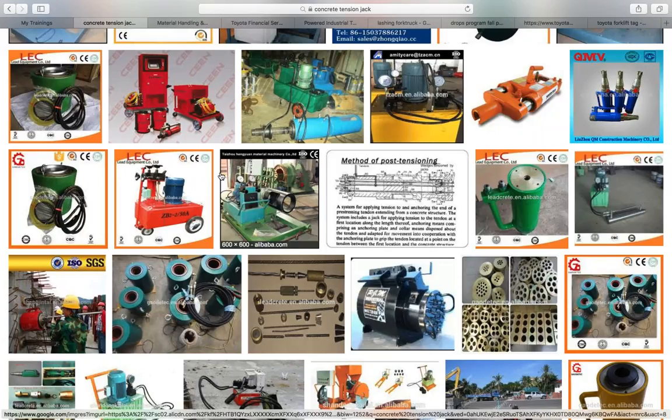We know that. Formwork has to be erected and braced in a manner that ensures it's going to support the vertical and the lateral loads. Bottom line, we can't have a failure. We can't have employees walking over rebar or concrete pouring where there's a collapse. So whether it's vertical or horizontal, it has to be made to sustain the weight.